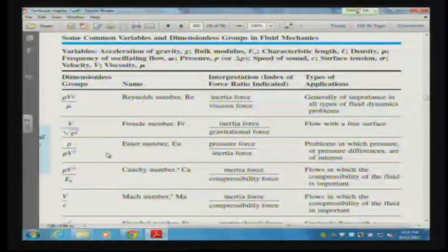Cavitation is, for example, if you've ever had a boat, sometimes the propellers on a boat will get all pitted up. It has to do with if you reduce the pressure below the vapor pressure, that you have a release of energy when the bubbles burst. And that can cause scarring on a propeller. There's a lot of other cases where the energy associated with cavitation becomes very important.